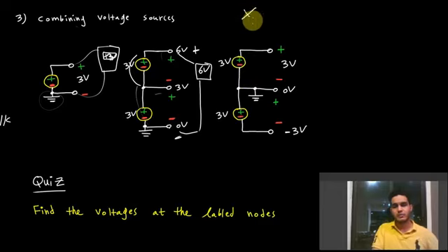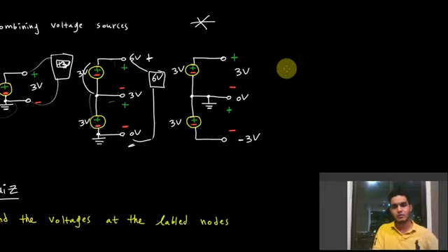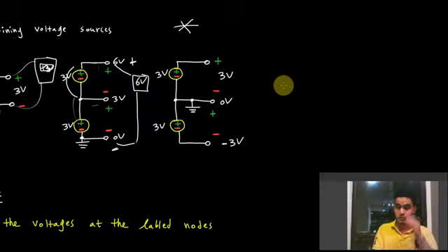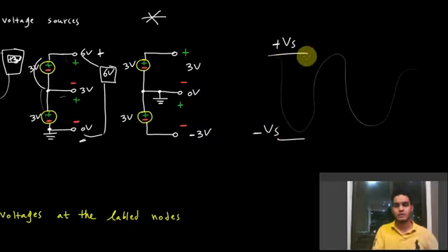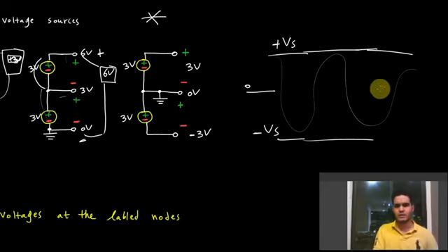Now here's an important example: when you have a dual supply, and this is useful for powering up op amps or amplifiers. What this does is it allows you to have a plus VS rail and a minus VS rail, in which you can have a certain swing. Your signal can swing in between. So you would have 0 here, and you have some swing, positive and negative. We're going to discuss that either later or in a different lecture series when we talk about amplifiers.